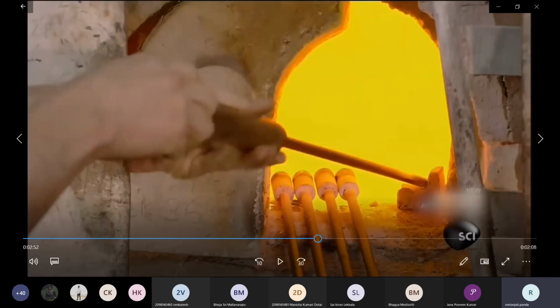Okay. Next, the next process is your blowing process. In the blowing process, what will they be doing? In the pressing process, what I told you, they melt the glass, then they press it against the die by various processes. It may be a manual process, or there may be machinery they can use for this. So by pressing against the die, they get the glass material. Similarly, the next one is blowing.